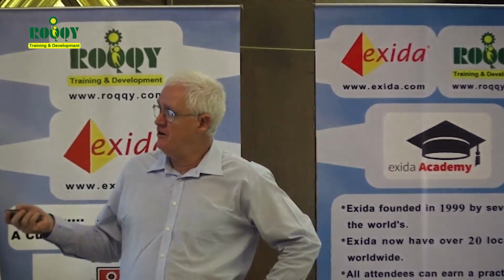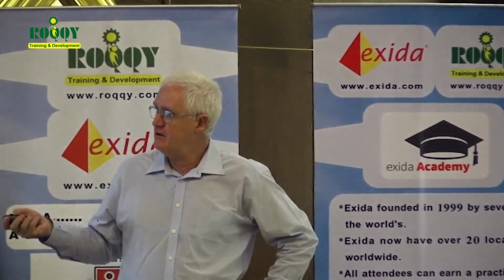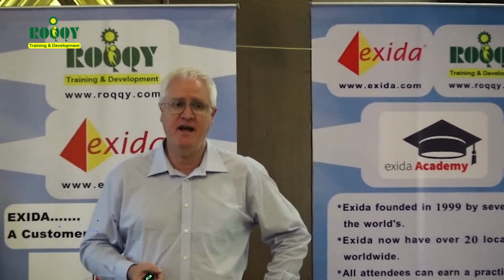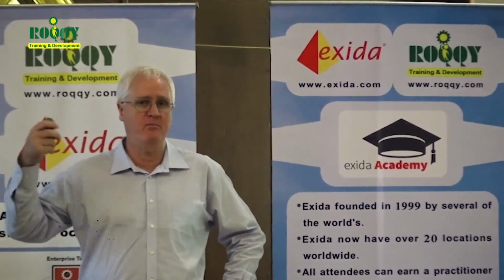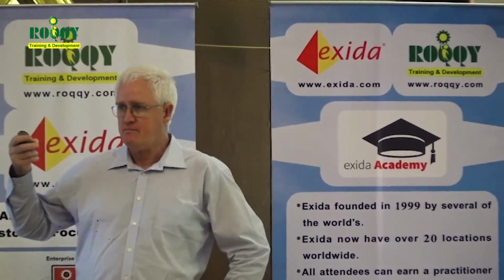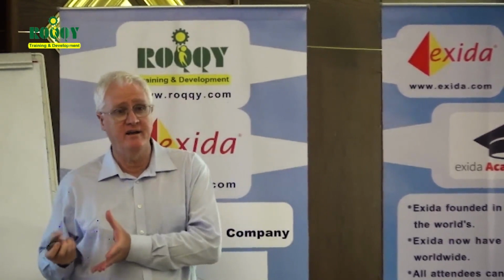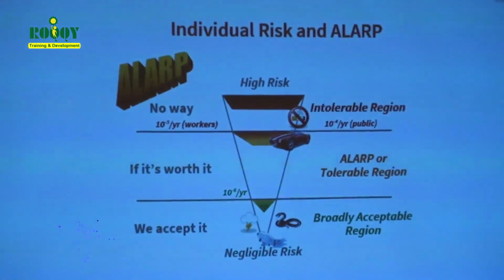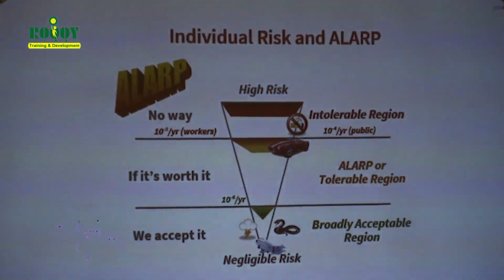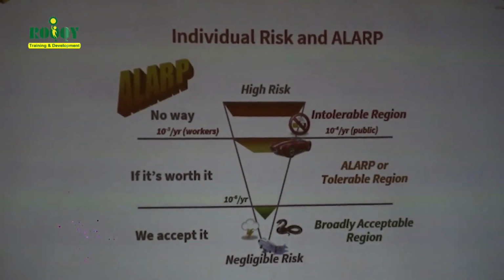If you land in this orange region, you have to demonstrate why you cannot get to the green region. You have to do an ALARP demonstration. ALARP stands for as low as reasonably practicable. You have to demonstrate that the cost of implementing any further measures far outweighed the benefit of where you currently stand.